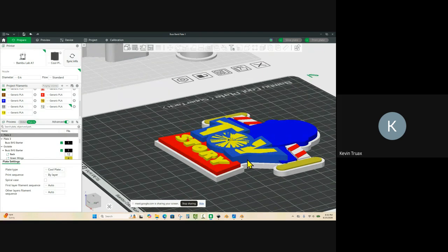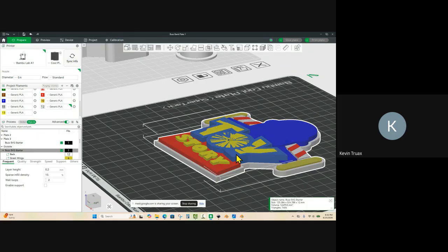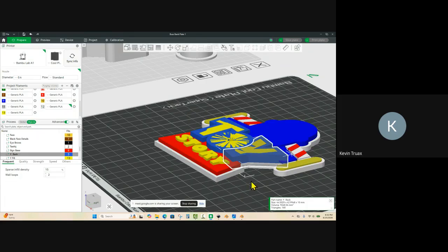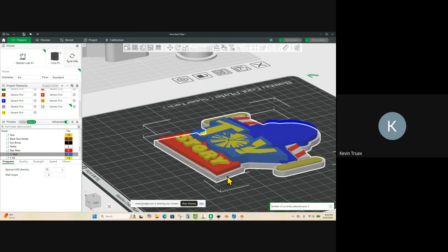By default, this comes in at 10 mil thick, and we want this to sit on top of our white plate. So what we're going to do is figure out where it exists right now. I think it's a little bit thick as it is, but let's see where it's at in the Z. I want to know where this face is. So we select that piece by alt-clicking just that piece, and then we can alt-click our plate, and when you come to the scale tool, it will tell us how thick those two are.